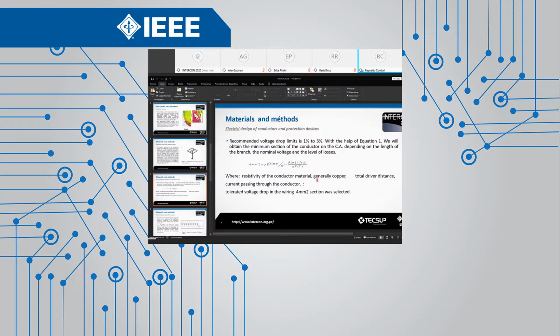With the help of equation 1, we obtain the minimum section of the conductor, depending on the length of the branch and the nominal voltage loss, where rho is the resistivity of the conductor material, generally copper, L is the total conductor distance, I is the current passing through the conductor, and the tolerated voltage drop in the wire is considered. A 4 millimeter section was selected.